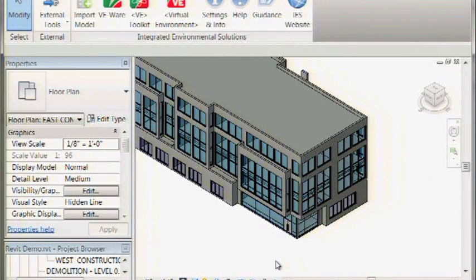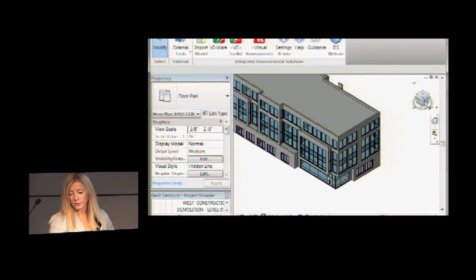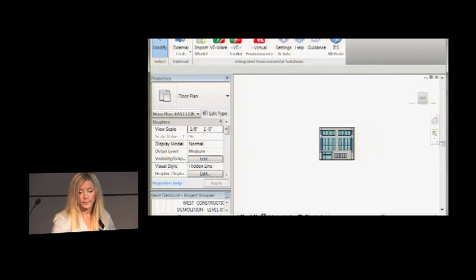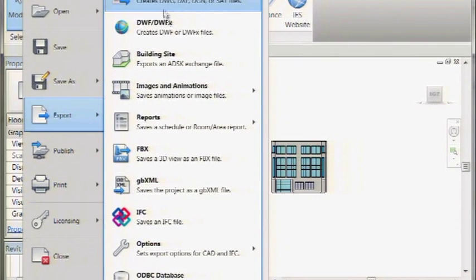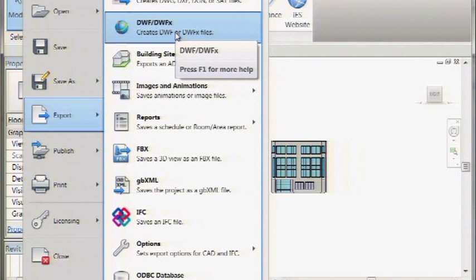Yeah, the issue is that because there's 100 individual rooms inside of here, you would first have to get rid of all of the internal spaces, all of the internal floors and internal walls, delete all the rooms, then close the shell. But one way you can, when you're in Revit, if you go to your views, so if I go to a front view or a side view, and I go to export, I can export a DXF in a 2D plan